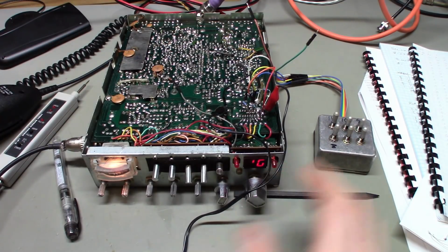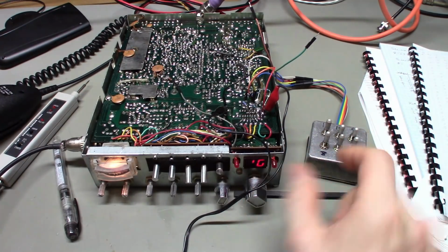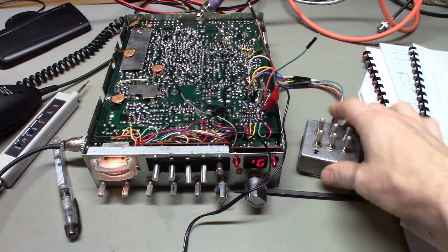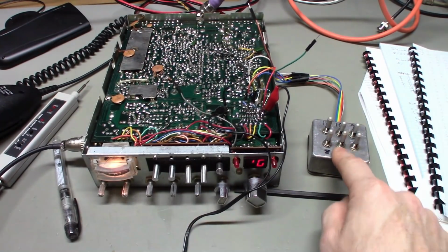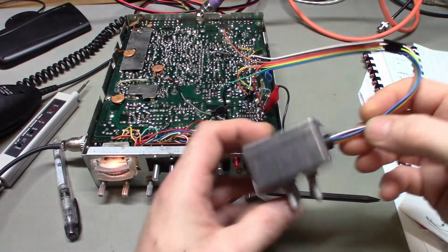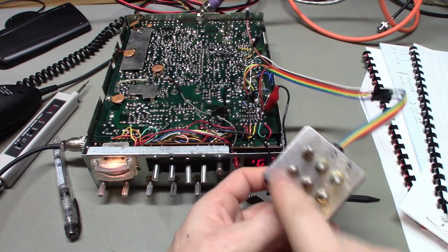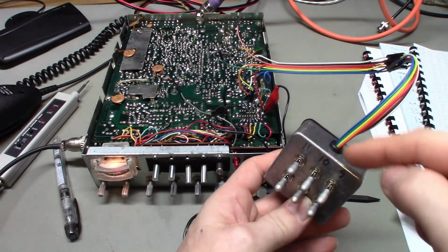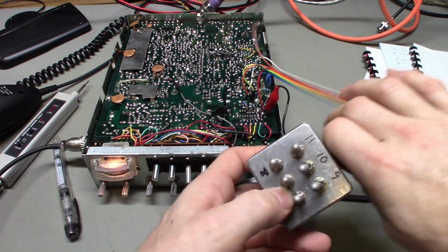My suggestion is use something like this. It doesn't need to be a metal box, but you can get those little plastic project boxes, basically the same thing. It's got a lid and four screws, but get a plastic project box, get some cheap ribbon cable. It's really flexible, and you can see even like here, I rolled it up so I could put it through a round grommet. But do the same thing. Put however many toggle switches you need in the box, drill a hole, put a rubber grommet. You can roll up the ribbon cable and shove it in the hole.